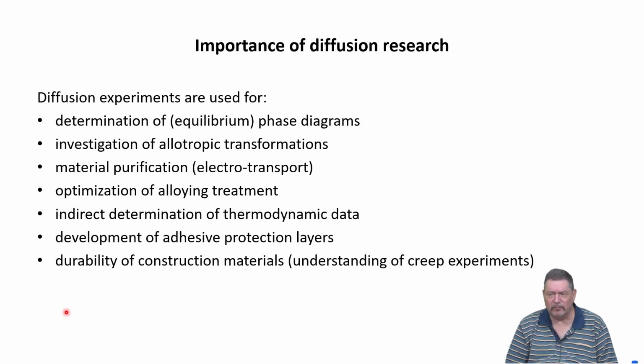So you really have to be aware of diffusional processes and how to use diffusion to your advantage. Because you will be using diffusion when you work in this area, whether you want it or not, because it is always involved in any transformation, in any kinetics of processing. And especially also in creep experiments, high temperature creep is governed by diffusion.